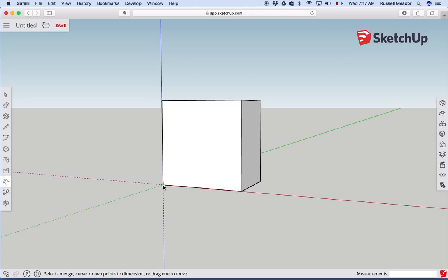So a quick, easy way to give dimension points for your client, you're just going to come over and click this guy on the left, the dimensioning toolbar. Then you're going to hit dimensions. And then I'm going to click this point and this point. And when I start to pull down, look there, just like your architectural drawings, it's giving you your 2 endpoints. And if I come here and down, there's my 2 feet. There to there, there's my 3 feet. And so you're able to show your client the exact dimensions of that base cabinet.